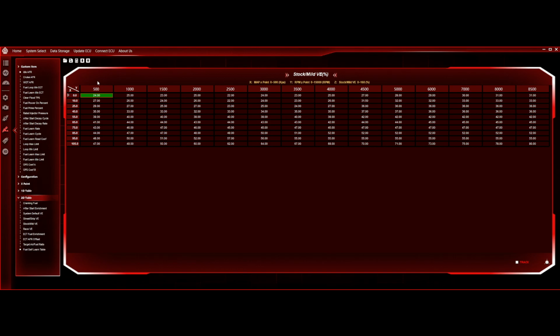So basically your ECU will pull your fueling from here. Say that at 25 kPa pressure at 2,000 RPM the VE is 27. We'll go to my target fuel at 2,000 and 25. We should be getting a 13.8 AFR reading. This is the commanded AFR. This is what we want: 13.8 at 25 kPa at 2,000 RPM.